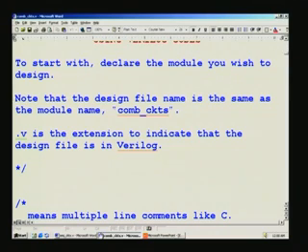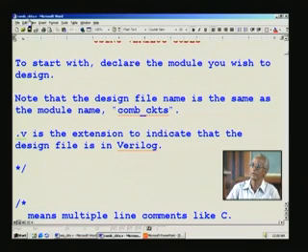So, make it a habit to use the very same notation even for saving it as a file. For example, the file, I wonder whether you can read it here. I will just read it for you. It simply means com_circuits.v. So, do not forget the extension .v to indicate that it is a Verilog and not VHDL. In VHDL you say .vhd as such. So, .v is the extension that you have to give for any meaningful name that you have here.